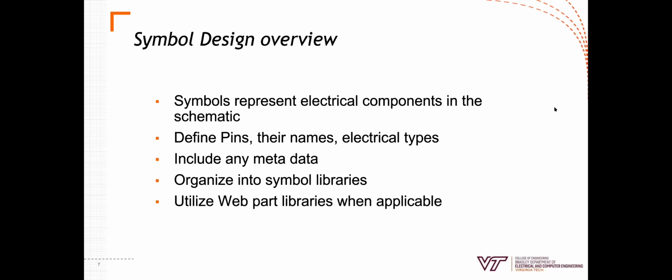So before you actually design your PCB, we have to make a schematic that represents the PCB, and it maps all the connections between your components before you go to lay everything out. When you place these different ICs, you need to have an associated symbol that represents the IC, and you can get these symbols from open source libraries.